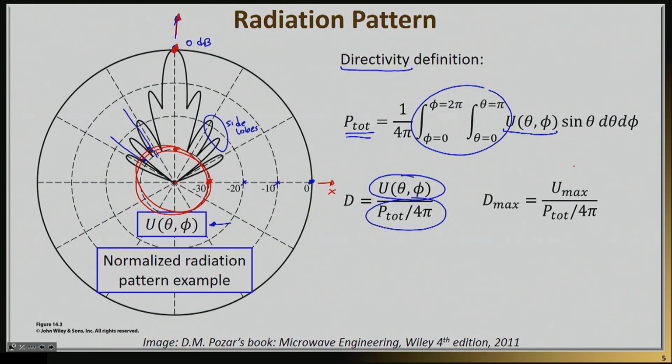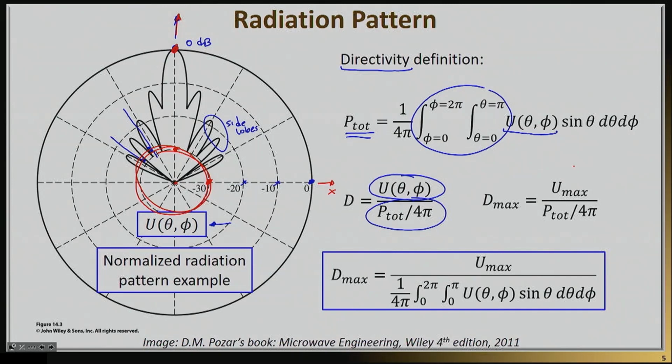And we will do this calculation and give you a number. For example, if the directivity is, let's say, 3, and it will be a unitless number, it means that in this direction, this antenna gives you 3 times as much power density as an isotropic radiator would have given you. What is really important to understand here is that there is no actual gain in the sense of an amplification. The antenna itself doesn't amplify its input power. It simply focuses on the right direction.